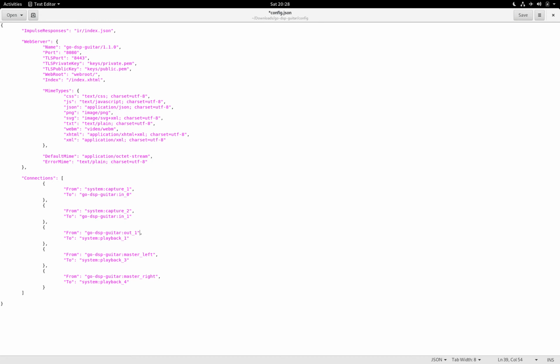Again, we're zero-based, and then output 1 to playback output 2. And this way I could go from outputs 1 and 2 directly, say, to a mixing console and take the processed signal from there, and then use the stereo mix down and route it to outputs 3 and 4 and connect my monitoring speakers and